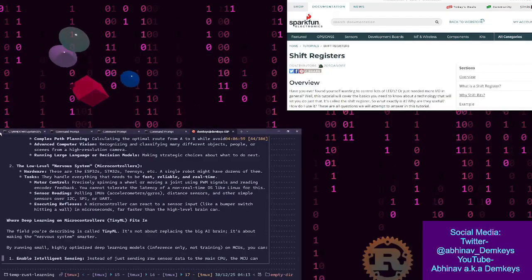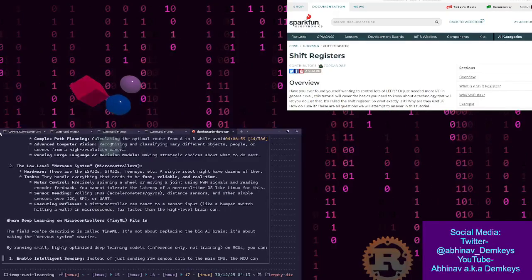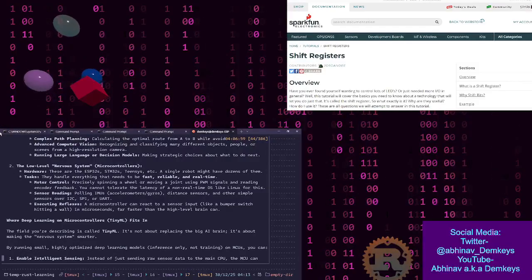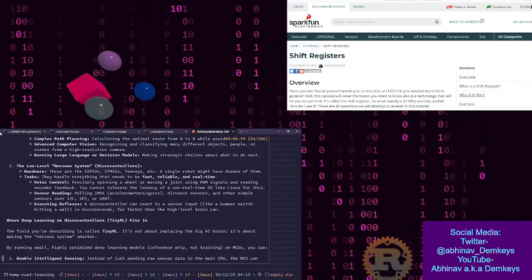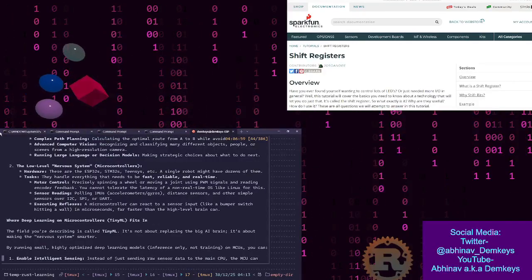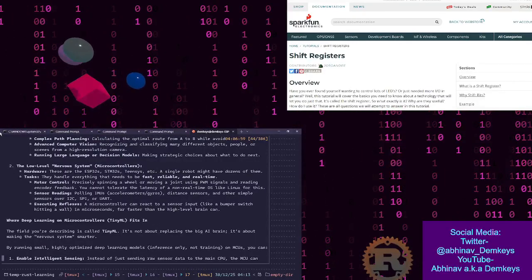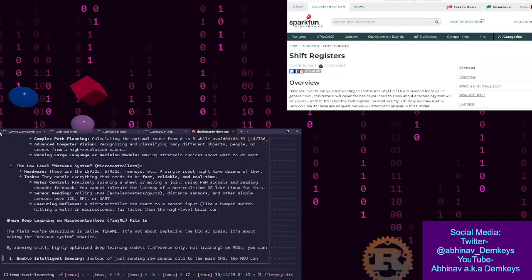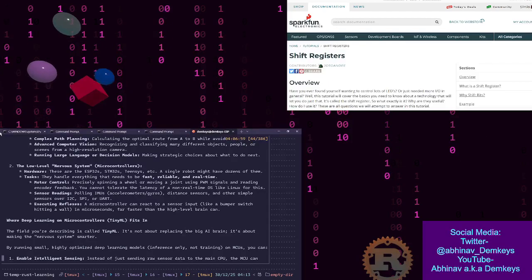The physical action completes an internal electrical circuit. Okay, the physical contact. When an external force pushes the bumper, it physically depresses the switch. Then the physical action completes or breaks an internal electrical circuit. Signal to controller. The change in the circuit sends a digital signal to the robot's brain or control system.